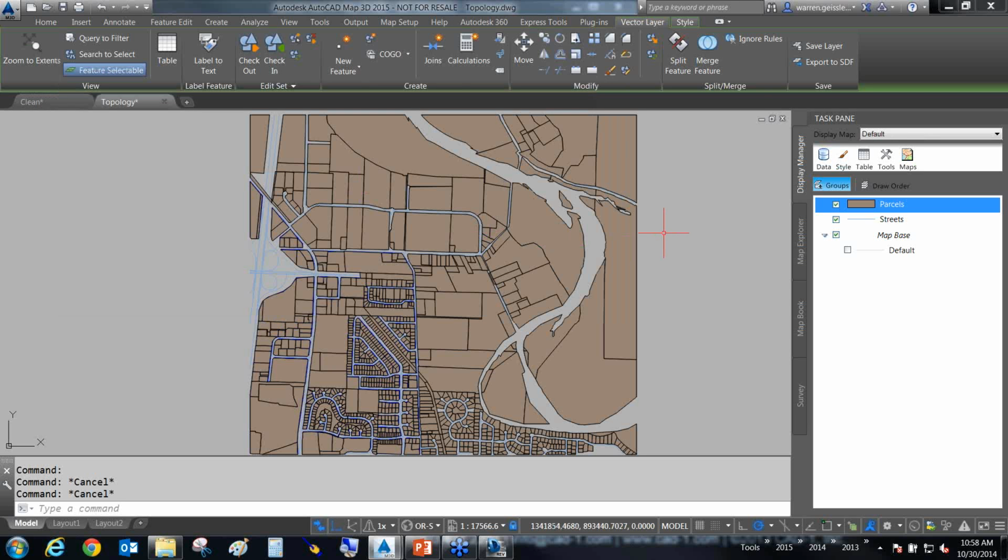So Sean asks, going back to the question about USGS elevation data: to link terrain geometry made from USGS elevation data to aerial, what workflow would you suggest? To link the elevation information to aerial, just do what I just did in here. Just attach the data. Make sure that your aerial is on top inside this list of the aerial, and then if you want to see it in 3D, down at the bottom of your screen inside of AutoCAD Map, you want to click the 3D button.